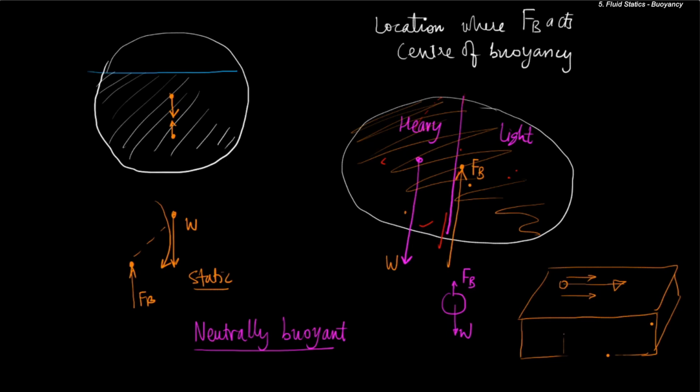Suppose the velocity in the lower part of the domain is low. So once the flow begins, if the particle is not neutrally buoyant, the particle will have a tendency to either sink down, where it will encounter lower velocities, or it will have a tendency to rise up, where it will experience possibly higher velocities. So it will not really give us the nature of the flow in the plane that we had injected the particle at.